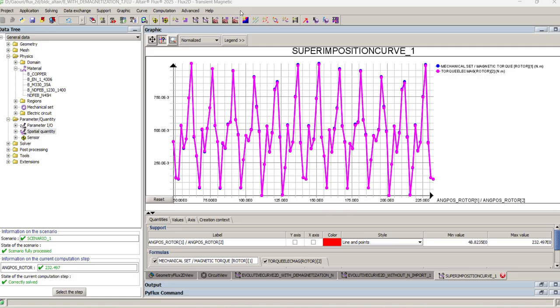So this was the workflow which I have followed to design the PMSM motor. I got 31 Newton meter torque with 94% efficiency at 3000 rated RPM. It states that the particular motor is suitable for EV application.